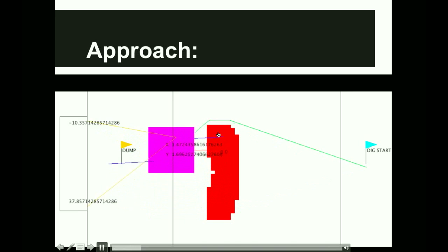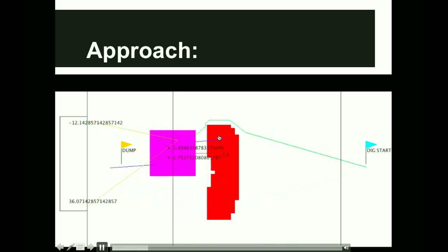Once you combine all of that together, essentially what you are able to do is report the angle at which the LED beacon is seen. That will locate the robot in the arena. There's a compass on the robot that will give you the heading angle. If the robot location is known, the obstacle detector is able to mark obstacles in the arena, and then an optimal path to a target is computed.